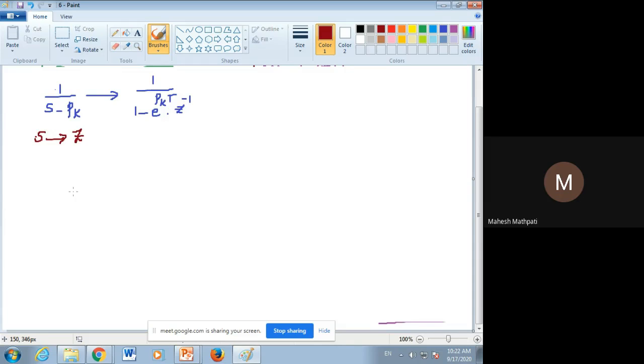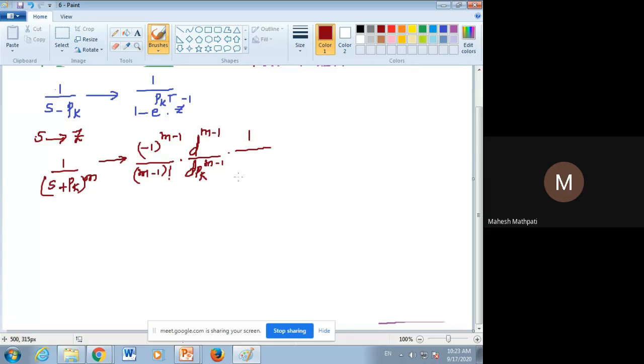So we can write, if we have first term as like 1 divided by S plus pk to the power m, it is like multiple poles we are calling, then its transfer function is written as minus 1 to the power m minus 1 divided by m minus 1 factorial into d to the power m minus 1 divided by d pk to the power m minus 1 into 1 divided by 1 minus e power minus pk t into z inverse.